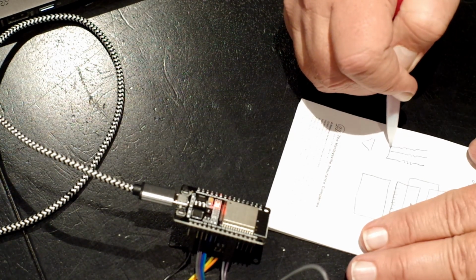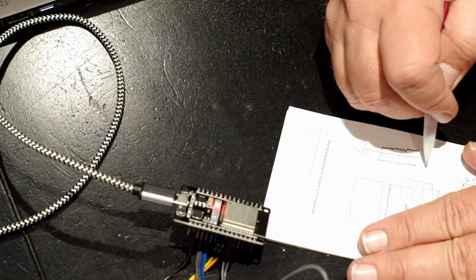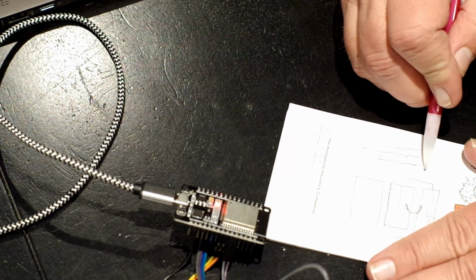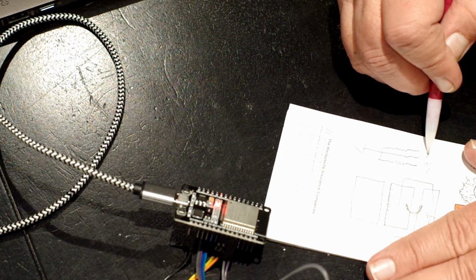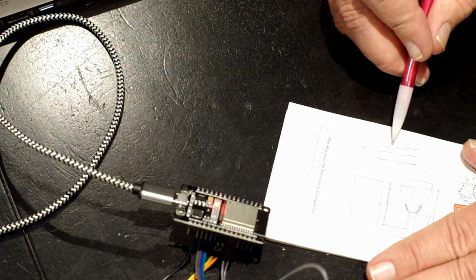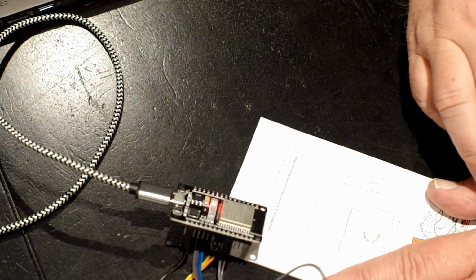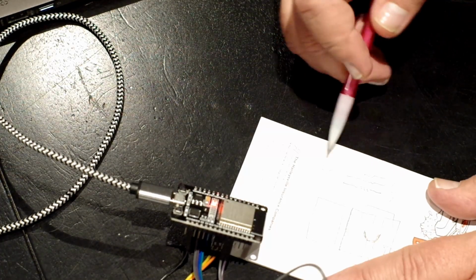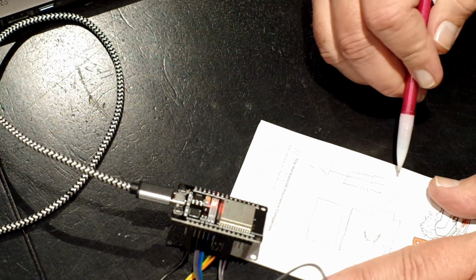These are tied together here and they're just feeding the op amp. Let's say on this side, if you have 1 volt here and 2 volts here and 4 volts here, this voltage summing amplifier will produce on the output over here 7 volts. It'll add them up.